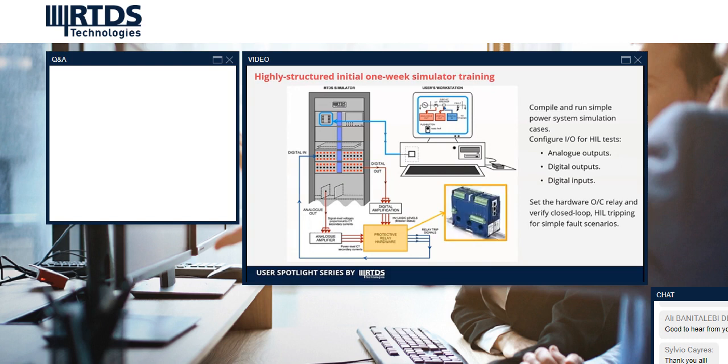But you can get modern equivalents of the same kind of relay if you're interested in this kind of approach. So you can get very simple, lightweight relays from a number of manufacturers. This one in particular is also a very simple overcurrent relay. You can activate one overcurrent element, and you can program it without needing fancy software. You can literally dial into it with an internet web browser and set the pickup level and the time dial level of the overcurrent element. It's a very, very simple relay that doesn't detract from the focus of the training.